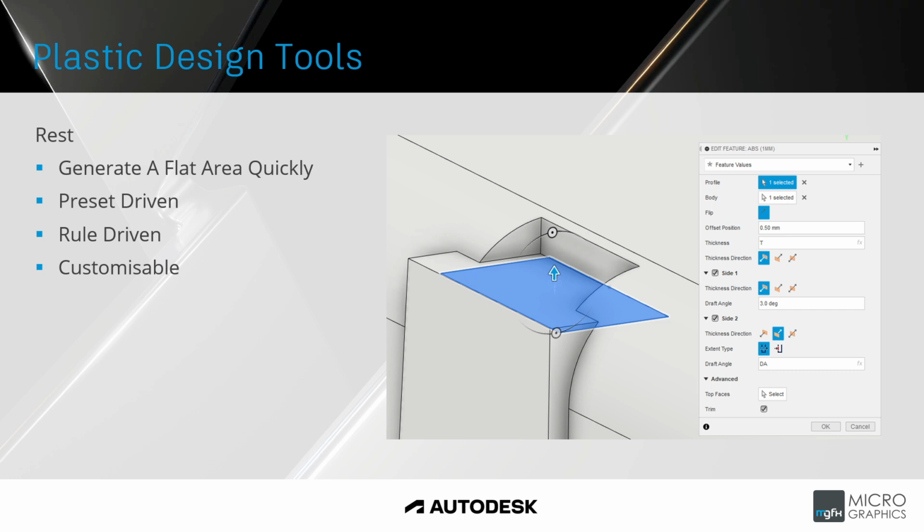We'll now have a look at the rest command. This allows you to quickly create a flat area on the model with the use of a single sketch. The command then takes care of the rest, ensuring that the part thickness is adhered to. Once again, this can be preset and rule driven to help with design decisions, and all options are customizable to allow you to meet design requirements. We'll see in the demo as well that sketch is parallel to the plane that we want to create that flat rest, and so we can also adjust the shape of the rest from within the sketch.